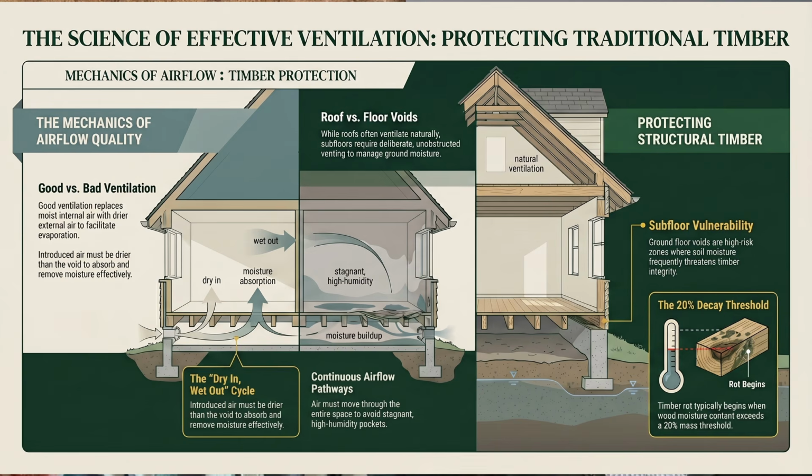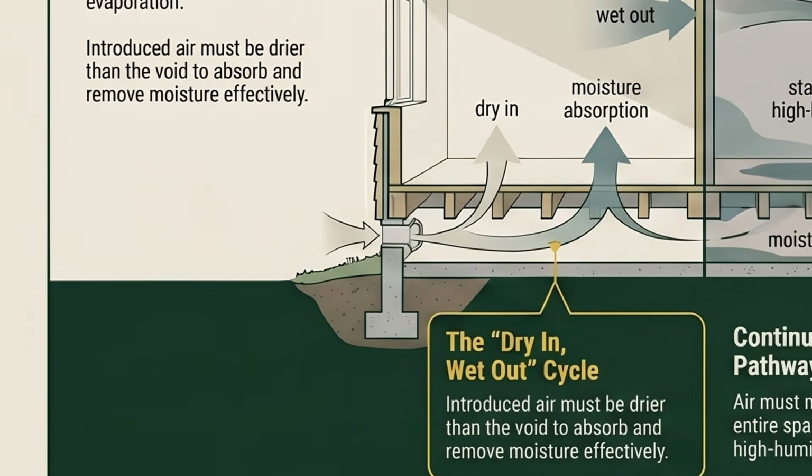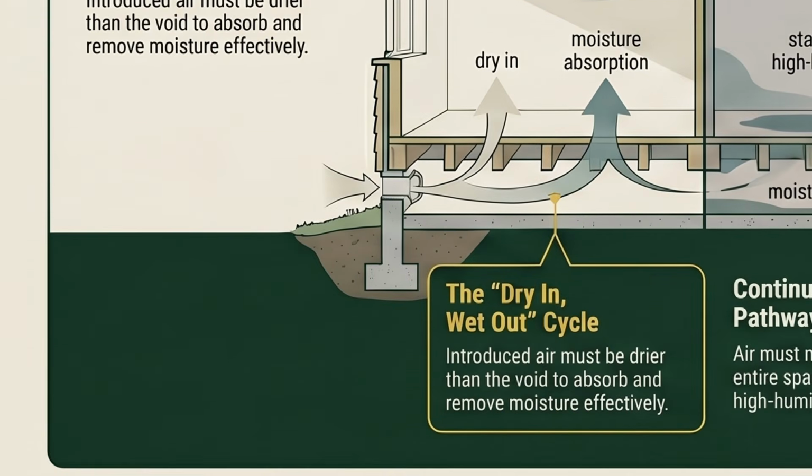So ventilation helps when the fresh air you're introducing has the capacity to absorb moisture into it and then take that moisture away. So you need the air coming in to be drier than the air within the void.